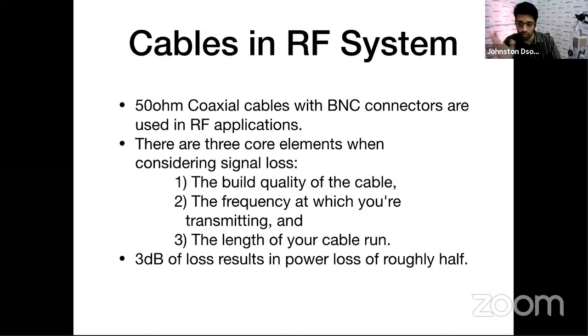We'll suspect some issues with the frequency will come. If you start getting losses, the first thing people go and do is start changing the frequencies. But many times it happens the frequency is not the problem, it's the problem with the RF cable. Maybe the cable is not shielded properly, and you start getting interference from outside. Okay, you start getting signal drop.